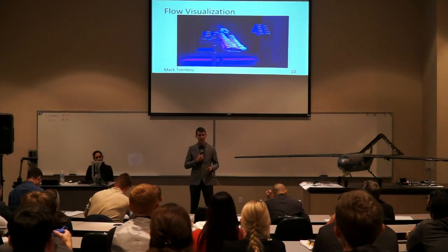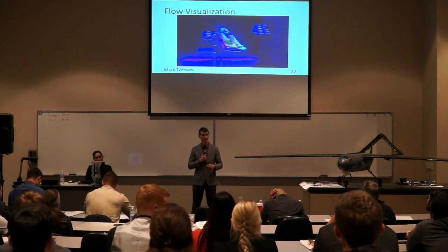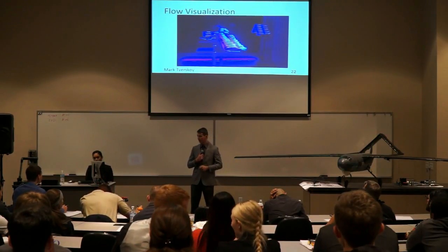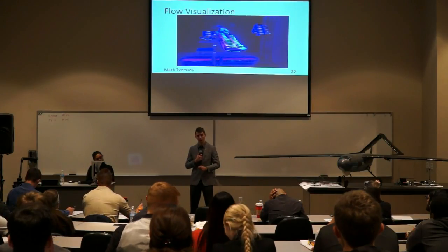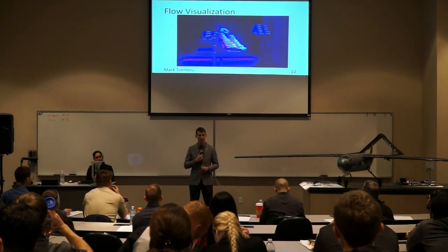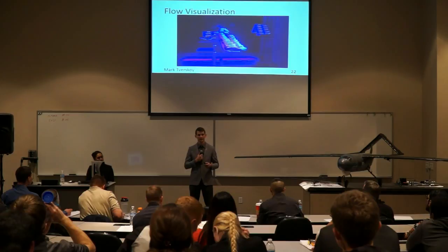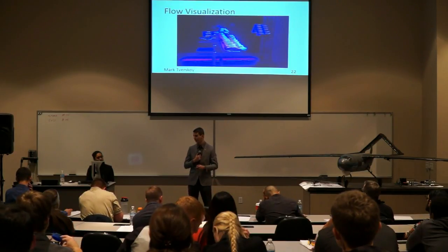The last stage of the wind tunnel testing was a flow visualization test conducted in UV light with tufts glued or taped to the wings, fuselage, and tail. The tufts showed how the airflow would move around the sting during flight. It showed that the wings stalled at around 12 degrees, as the data predicted, and also that the tail did not stall at angles of attack as high as 18 degrees, indicating favorable stall characteristics, which would make it easier to fly.